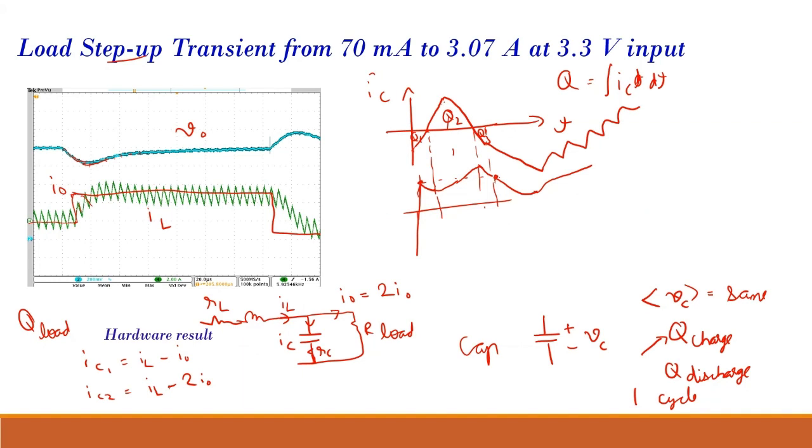Sir, the voltage across the capacitor can't change instantaneously, right? Yeah, it is not changing instantaneously. Over here also, if you see, it is not instantaneously changing. It is reducing. This is your V output. When your inductor current is not instantaneously changing, it is increasing gradually till it finally reaches the next steady state condition.